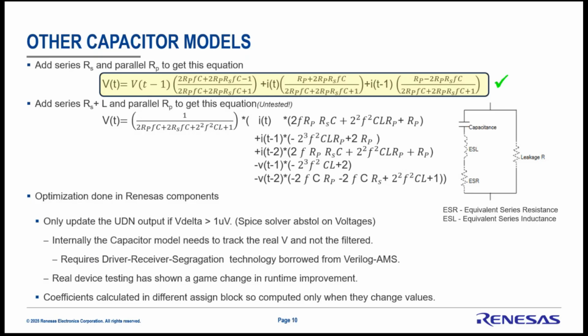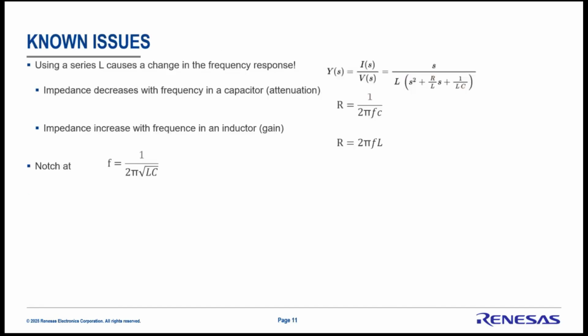The other thing is there's no point in calculating all those coefficients each time. You know, you're not going to be dynamically changing the resistance all the time. So those can be just calculated once. And that, again, these always loops are toggling quite often. So if you can make a single optimization like that, it makes a big difference. Some of these things will have, you know, up to 500,000 events in a simulation, if not more. So cutting out a line of code makes a big difference.